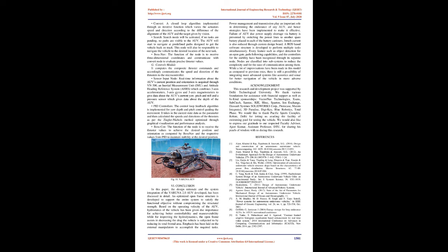We have used 3 parallel PIDs to tune the pitch, yaw, and depth of our bot. The method we have used for tuning these is the Ziegler-Nichols method. This is a heuristic method that produces good values for the following parameters: Kp, the controller path gain; Ki, the controller's integrator time constant; Kd, the controller's derivative time constant. By varying the 3 values above, we can directly see the effect of it on our bot. This way we can tune our bot for pitch, yaw, and depth in real time with accurate results. This method is a bit time consuming but provides accurate results.